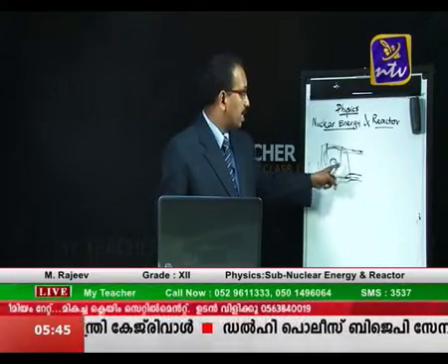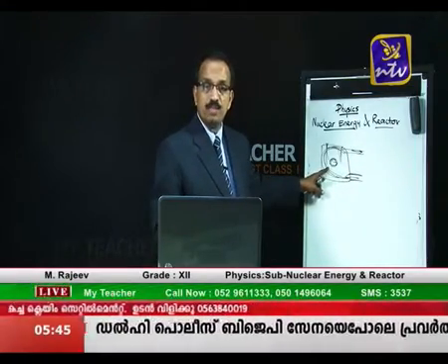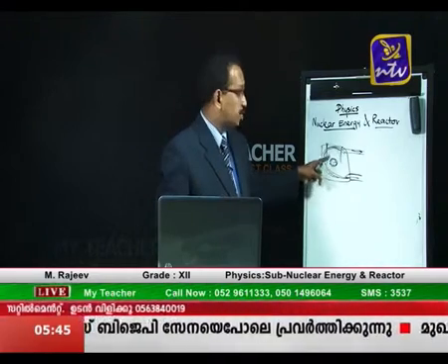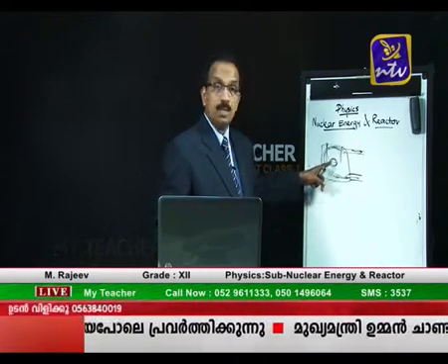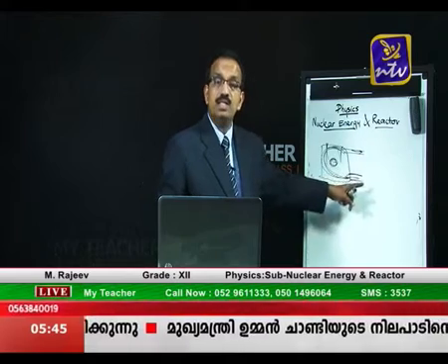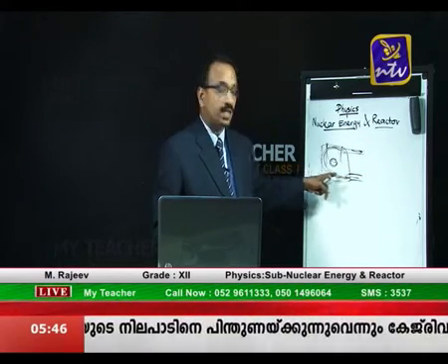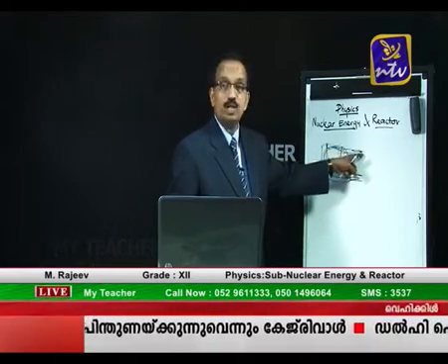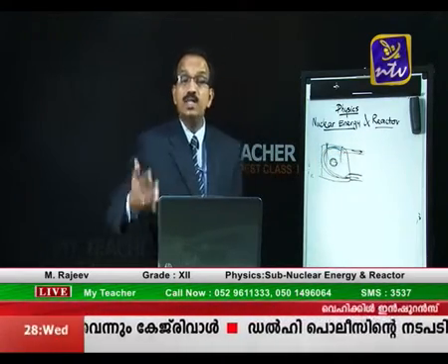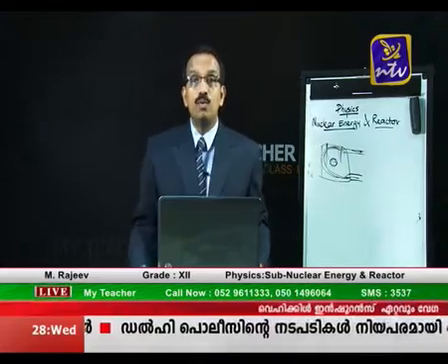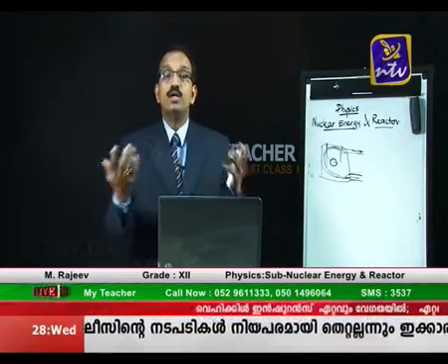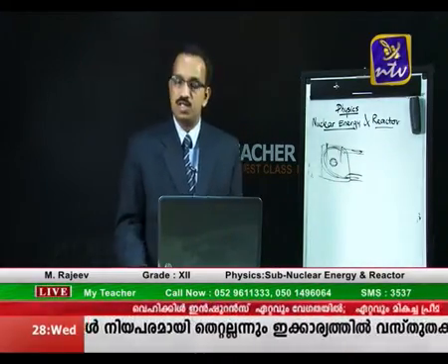So once again, in the core the chain reaction happens. The fuel is kept in the core, the chain reaction happens, and a large amount of energy is released. This heat is absorbed by the coolant given to it. That coolant comes out as a very hot liquid, and this heat is utilized to boil water to produce steam, rotate the turbine, and produce electricity.